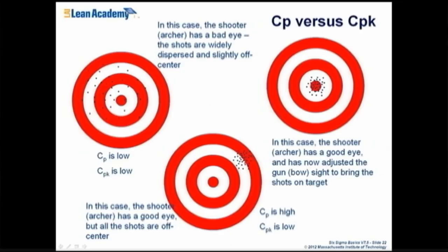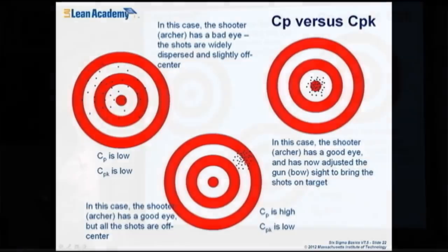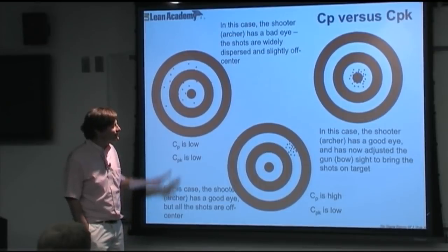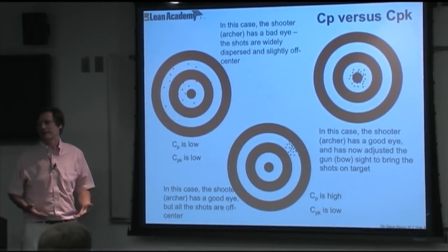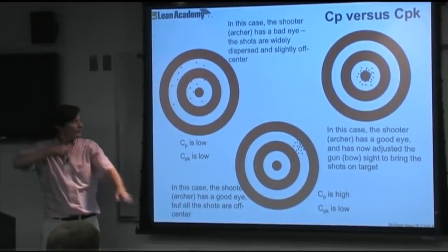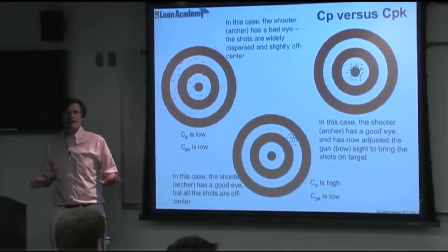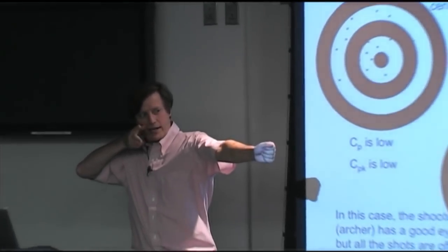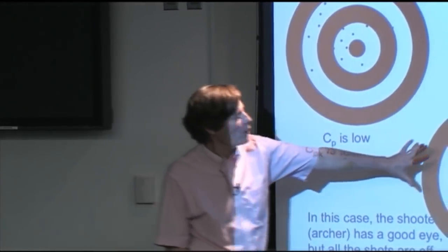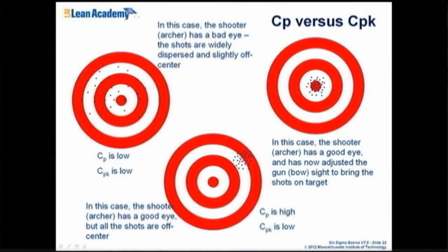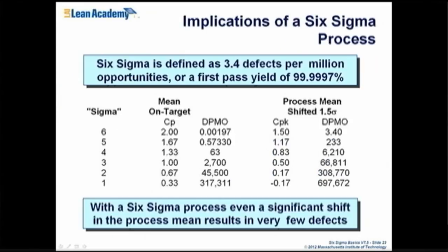If you're an archer or any other person who needs to control their process, what do you do first? I'm cheating a little bit on this one. I do archery sometimes, not very much. But you have to do this first, actually. You have to get your process repeatable, even if the mean is way off. Because if you're correcting every time, then it just goes all over the place. But if you go, okay, same thing every time, five times in a row I've hit up and to the right, now I'm going to adjust. So often you concentrate on knocking your CP down first to understand your process, to see where the mean is, because you can't really measure the mean in a situation like that. You can statistically, but it's hard. Okay, enough of that.